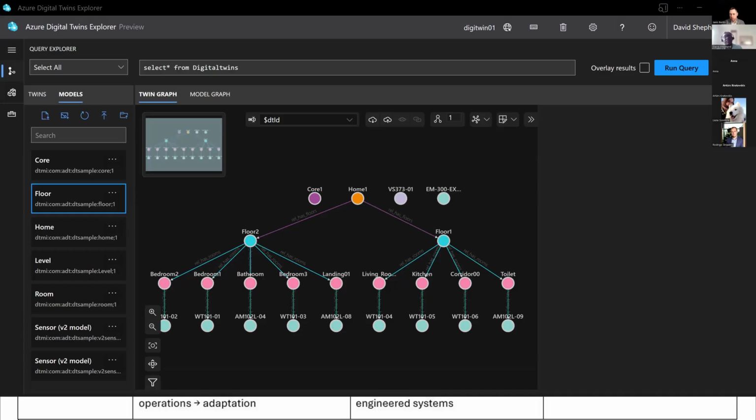The platform that I'm accustomed to working with, and this is not to say that's the only platform that does this, is Planon. Planon has a mobile app, and the mobile app allows you to see the 3D model. If you're in a particular space, you can locate a particular asset in that space and your maintenance team can start to input data that's connected to that representation. So you upload the model, and there's a unique identifier that links to the data in the computer-aided facility management system, and that's how it works.